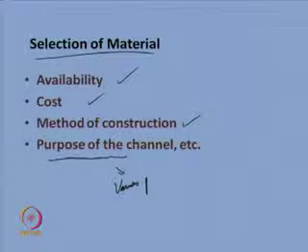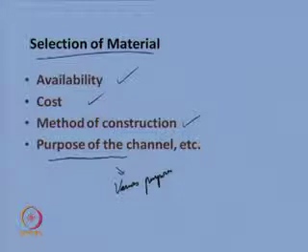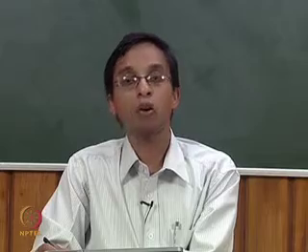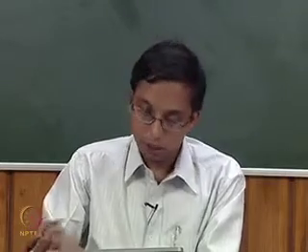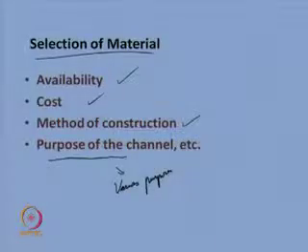So, you have to adopt the materials accordingly. If it is a waste carrying channel, definitely if you use timber or steel, steel may react with the various chemicals in the waste and your channel may get eroded. This is chemical erosion that may occur there. So, you have to avoid such things.